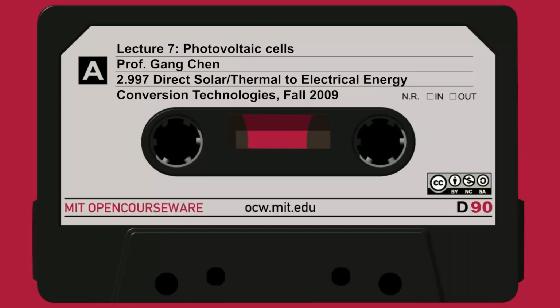Okay. And everything is very similar to what we had before, except that A is a lot longer. If you look at the diode, this is the A for the diode. That's determined by radiative material recombination. And this is really just the dielectric constant, refractive index, and band gap of the material. So this is the maximum you can have. The best you can have.